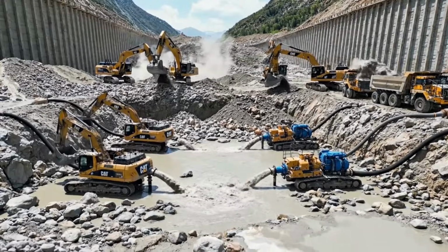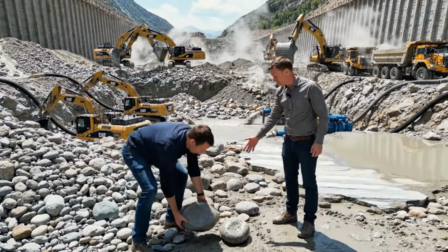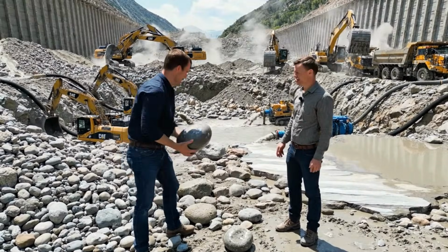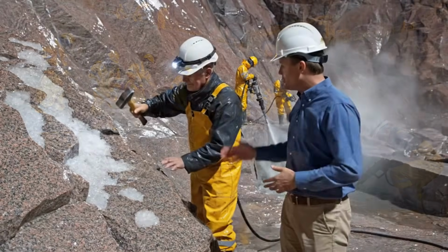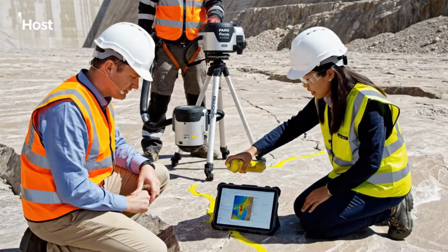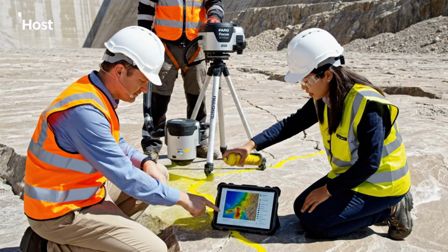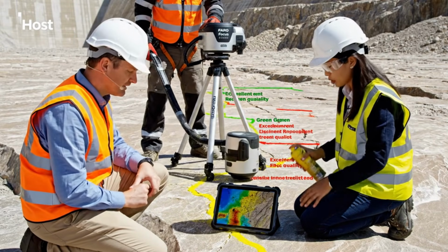To get to the foundation, they first have to clear all of this, like this massive river cobble right here. They're using 3,000 PSI water jets and pneumatic scalers to expose this pink-gray granite. It's a massive undertaking. We are marking this linear fracture in yellow, which means it requires grout injection. And the scanner captures that in the 3D model immediately. Yes, look here on the tablet.